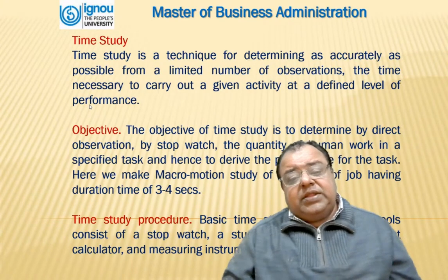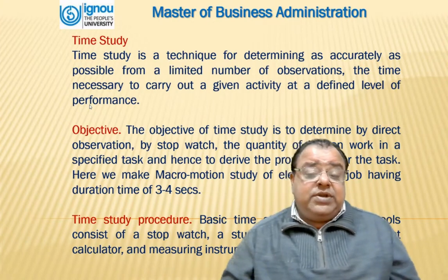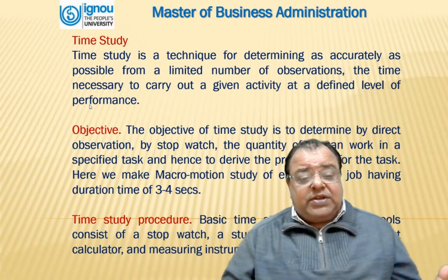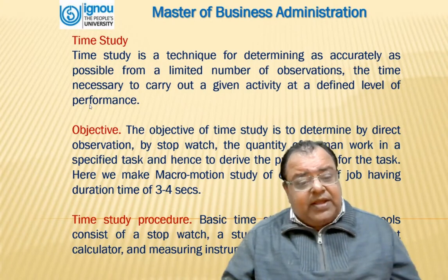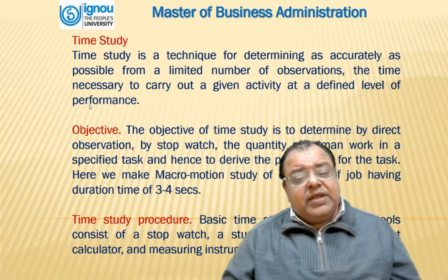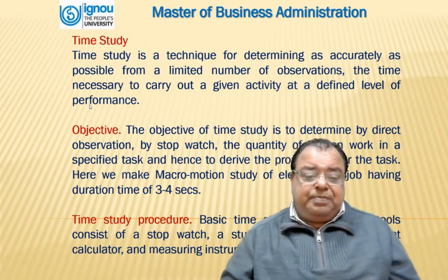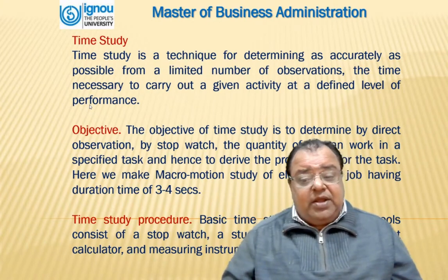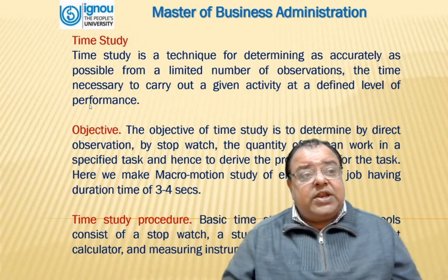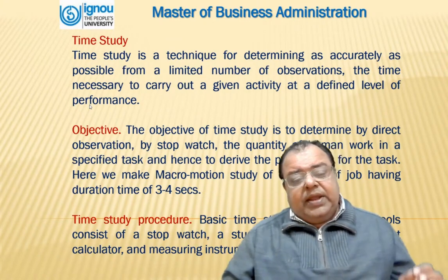The objective of time study is to determine by direct observation, by stopwatch, the quantity of human work in a specified task and hence to derive the proper time for the task. Here we can make macro motion study of elements of a job having a duration of 3 to 4 seconds.